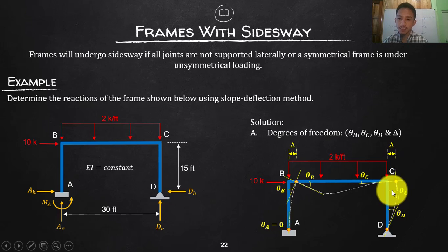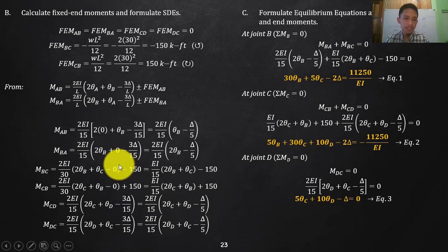If that is the case, that C goes down, then you will have delta 1 going horizontal and delta 2, which is the going down. But in our case, there is no relative deflection of DC, so that will still be 0. And the fixed moment, you have it there. So this is your moment equation.